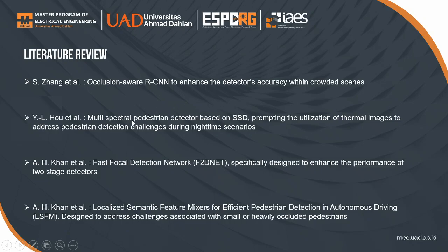We had also the multispectral pedestrian detector based on SSD, prompting the utilization of thermal images to address pedestrian detection challenges during nighttime scenarios. Also, we had the fast focal detection network, or F2D-net, specifically designed to enhance the performance of two-stage detectors, and the localized semantic feature mixers for efficient pedestrian detection in autonomous driving, which is called LSFM, and which was designed to address challenges associated with small or heavily occluded pedestrians.